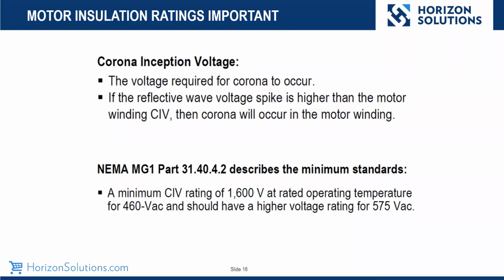Just keep in mind too, if you do have 575 in your plant, you might want to check with your manufacturers. 575 reflected wave becomes more predominant as the voltage goes up and the lead lengths go out to the motor. Next slide.